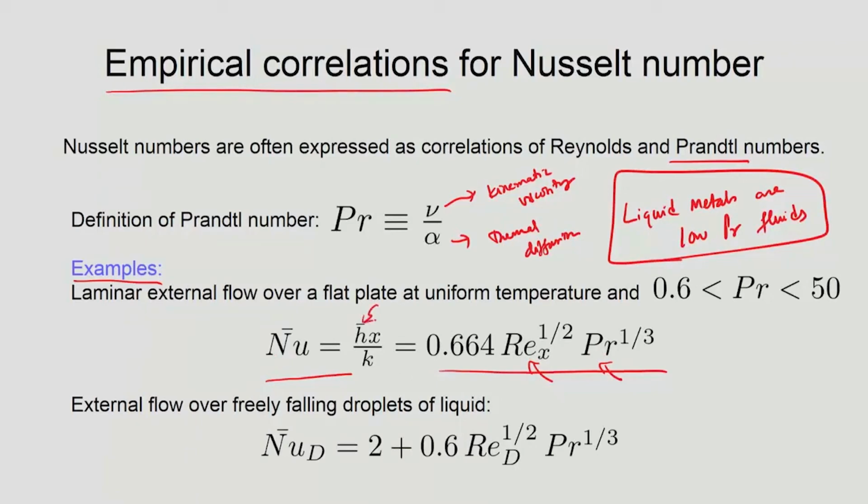So, for example, if you say that I have changed the gas that is cooling the flat plate from argon to helium, then how much will the heat transfer coefficient change? You could see that it comes via this, okay, because of the Prandtl number, because in the Prandtl number you have got alpha, and alpha is going to be different from argon to helium; it will be more, and straight away you can then see how the h will be changing. And then if you say that the flow rate of that gas is doubled, what would happen? Then we see that it is the Reynolds number that is changed, and you can see how the heat transfer coefficient is changing like that.